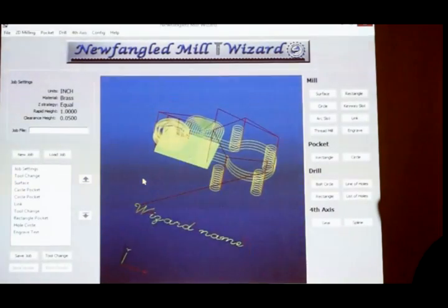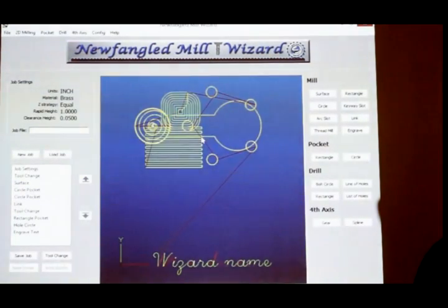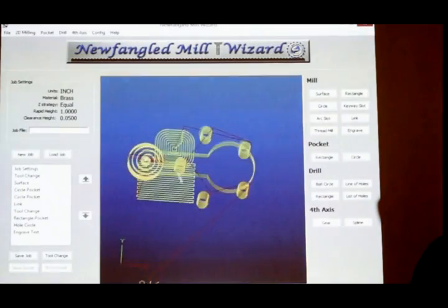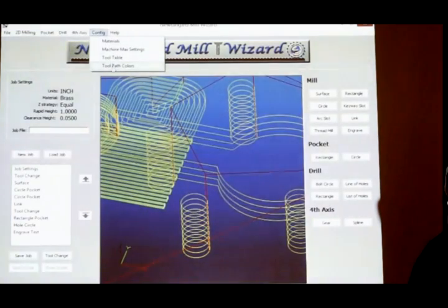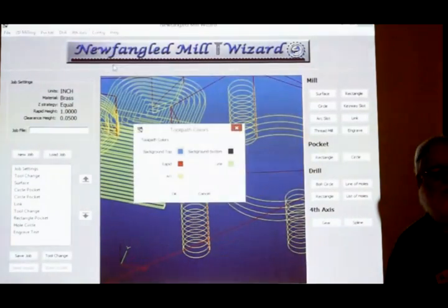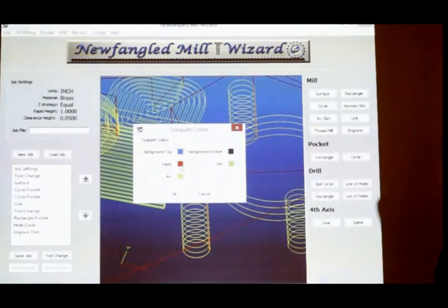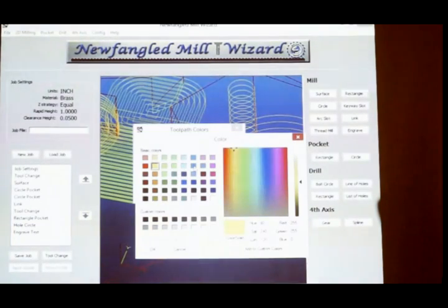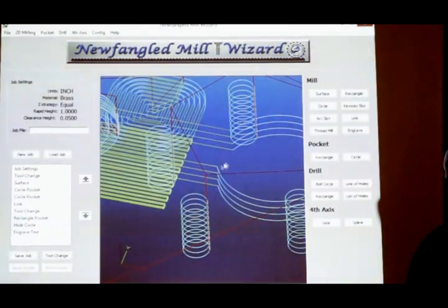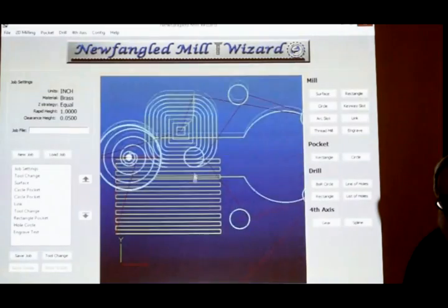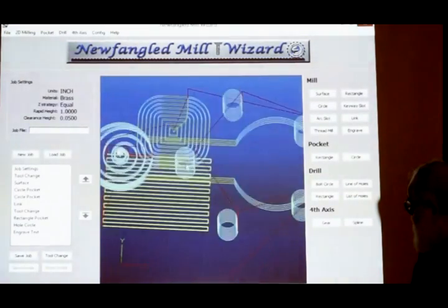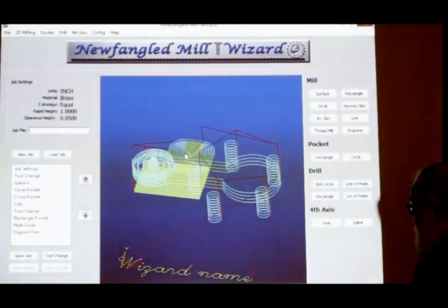So if you're doing tool changes in your arcs, well, we've got that arc slot where you can make arcs. I think it always uses Mach's IJ itself as incremental. We don't have configuration associated with the tool change command. So this is just going to give you the G-code for a tool change, and whatever you have inside of Mach for the configuration is going to determine whether it pauses, changes my TLOs, and all that. Yeah, that's your configuration inside of Mach 3 that's doing that for you.